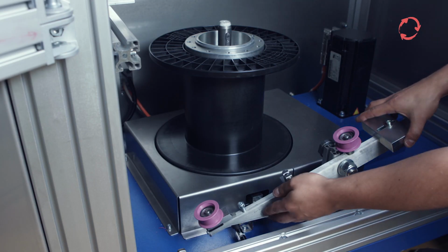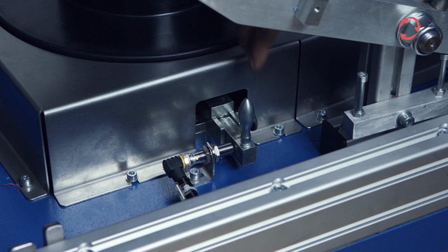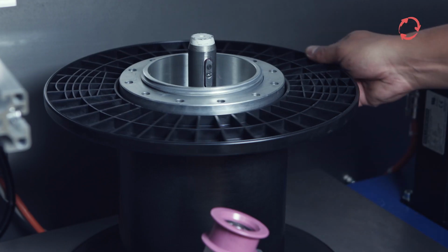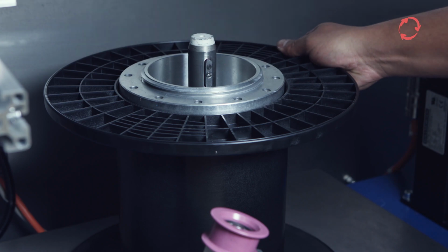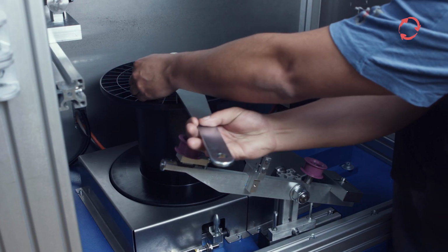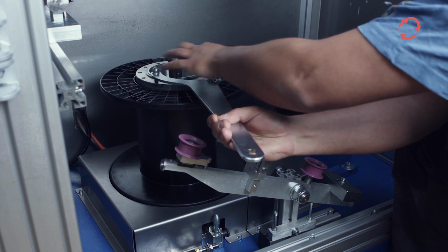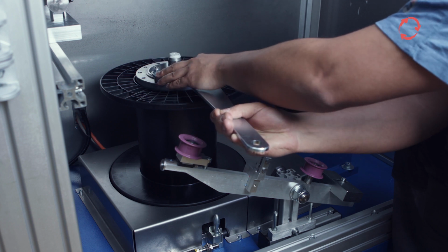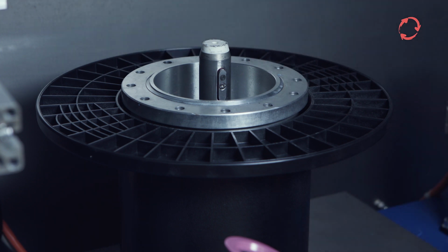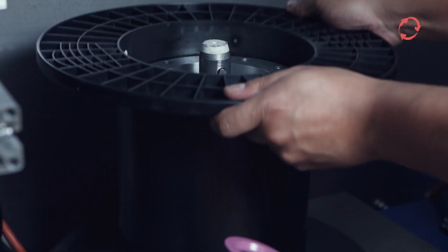Lock the spindle and coil by pulling out the black safety mandrel and pushing in the slider. Turn the spool until it clicks into place. Now the small LED has gone out and the coil is locked. Open the clamping disc with the hook wrench and remove the coil. Now the new coil can be used.